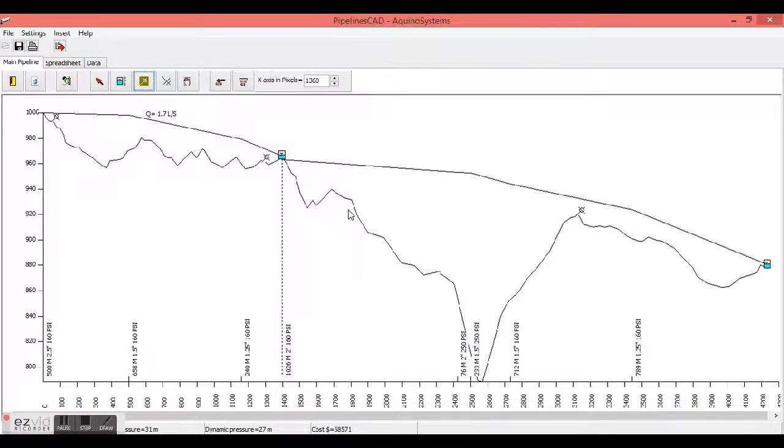Normally, the surveyor indicates some sections where it will be necessary to place a specific type of pipe, such as the case of rocky soil or bridges, where it is specified that galvanized iron must be installed. In our example, suppose that we need to install galvanized iron from stations 1700 to 1800.